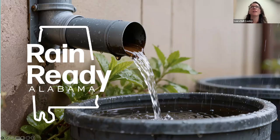If I'm understanding that question, they might be referring to the fact that you often see riprap, or rocks, put along eroding areas in a stream to help with stabilization. My first take on that question would say that's not necessarily the route you want to go to. I think rocks are often really helpful in disrupting the amount of volume that could be coming from, I think you said, a storm drain or something like that.